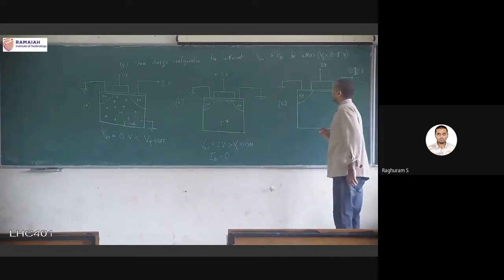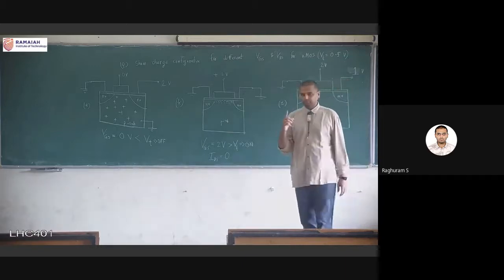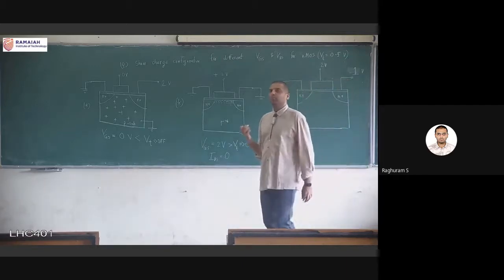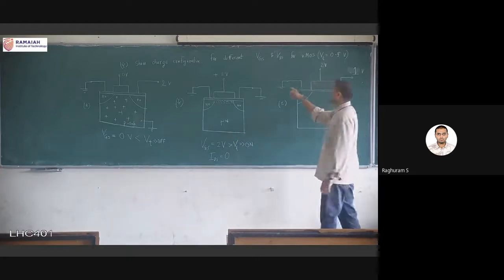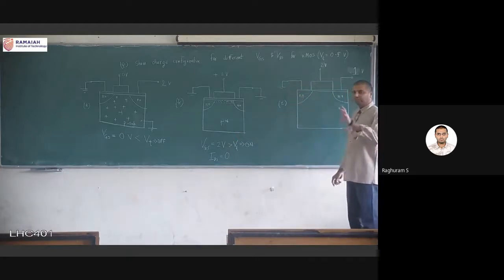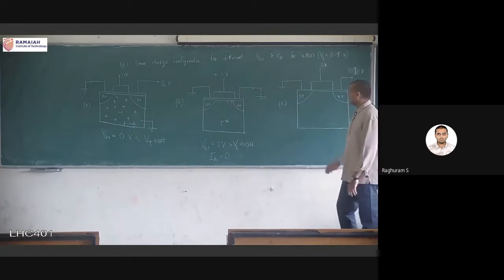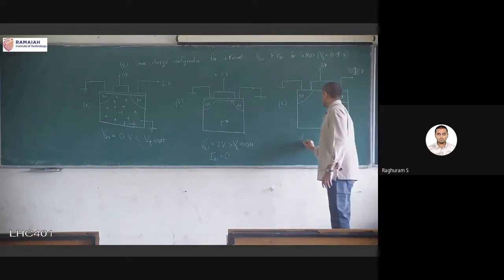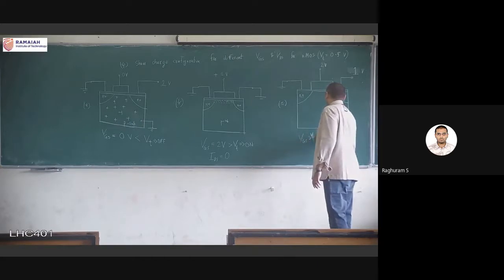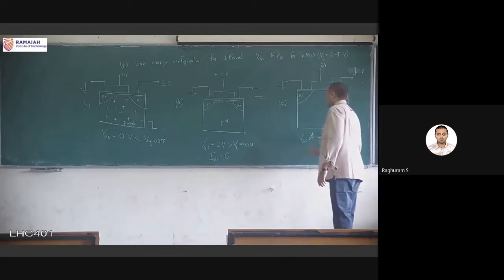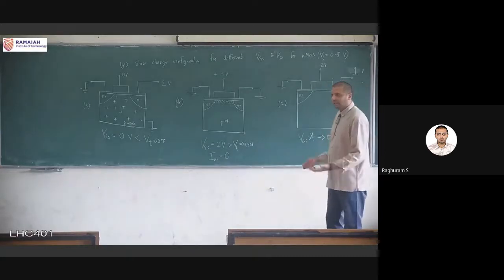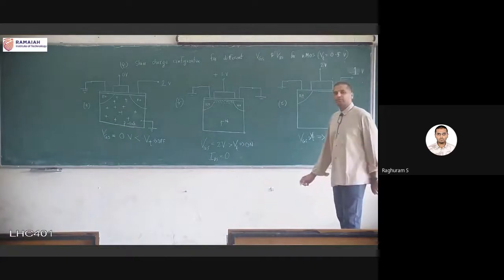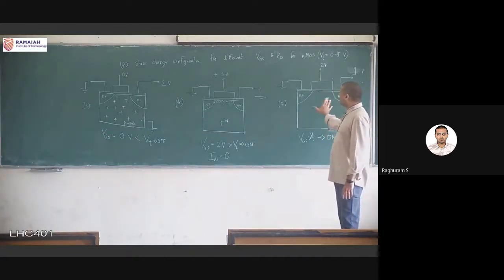Okay, so we are giving 1 volt to the drain voltage, and since the source is 0, VDS equals 1, VGS equals 2. So VGS is definitely still greater than VT, so it is on. Okay, this much is true. Now, before we look at the current, we can't calculate the current yet. There will be some current flowing for sure. Let us look at the charge configuration.